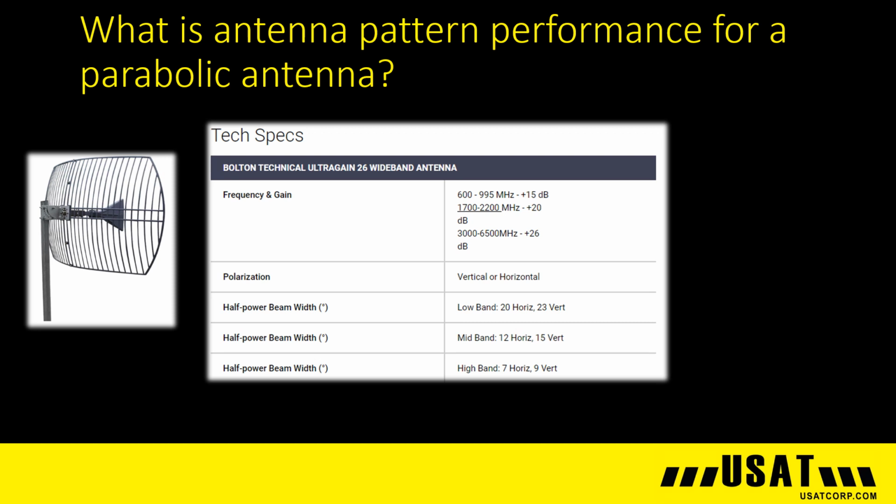I touched on earlier the antenna type that could be considered an extreme edge of connectivity cases, and that would be the parabolic antenna. Parabolic antennas are best used in point-to-point applications and rarely used for cellular. The main reason is that the peak gain over frequency varies a lot. So if you have connection on band 4, then the carrier tries to move you to band 13, it may drop the connection. In addition, the beamwidth is so narrow, you will have great difficulty in aiming it, and you will need to keep it stable. You should really only consider these as a last resort, and you will need 2 of them, of course, for LTE.